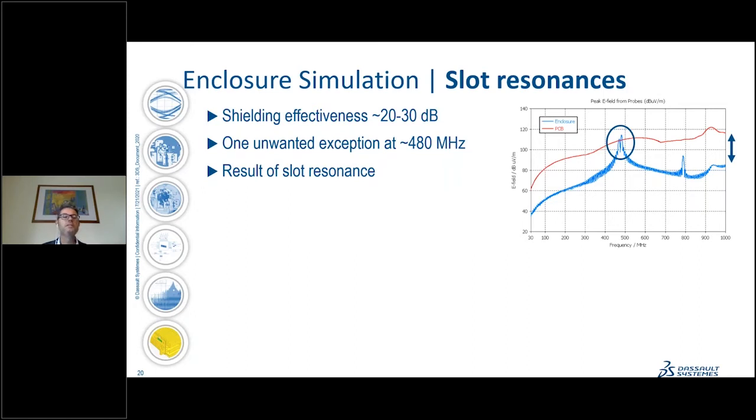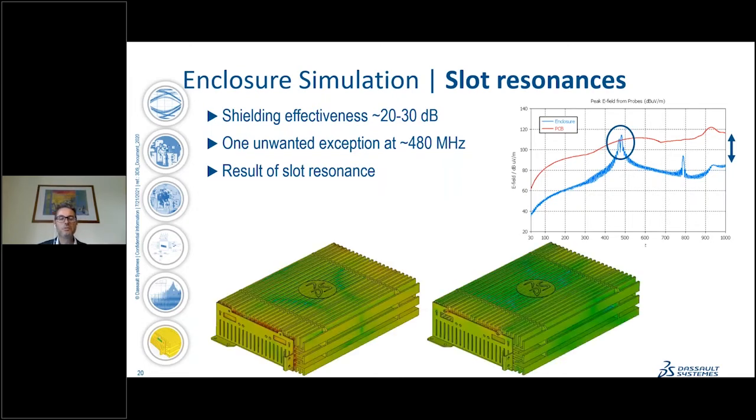You have something at 20 dB. Unfortunately, at a certain frequency, a bit below 500 megahertz, you have a resonance. That means that with the box, it's even worse than without the box. So we need clearly to do something. And this is what is done here.